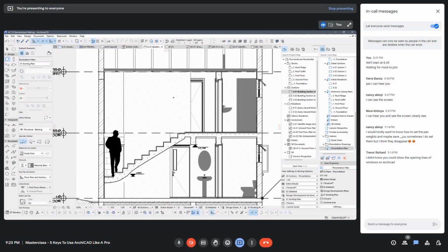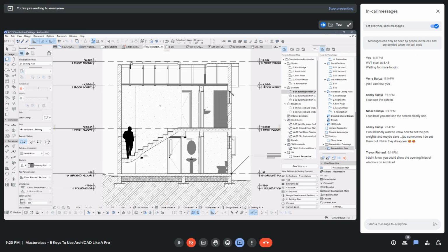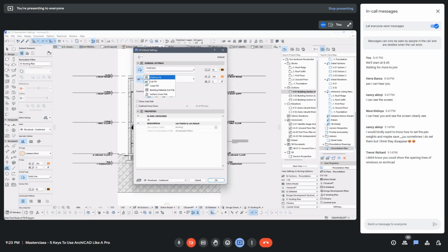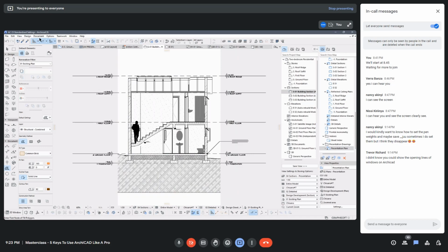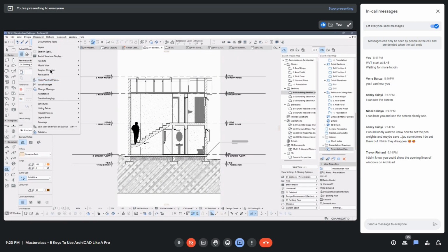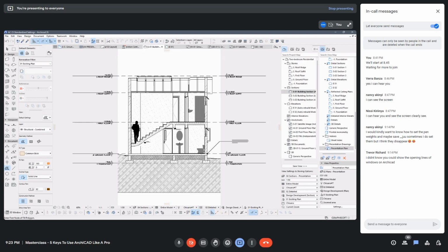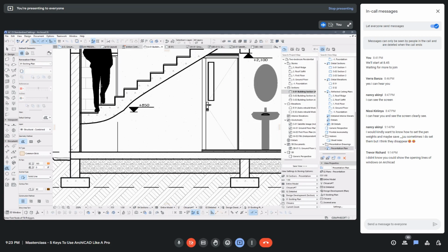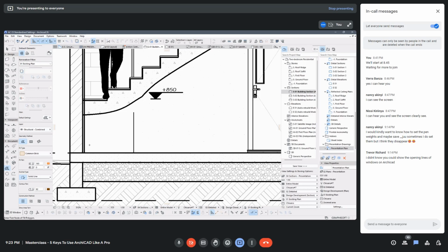So a cover fill is the fill that 3D elements show with, but drafting fill is if I were to draw any kind of fill here. Now ArchiCAD asks me, is it a cover fill, is it a drafting fill? So you can dive as deep as knowing what it is you're editing. So that's that on graphic overrides. At the same time, I also asked ArchiCAD to show transparent.